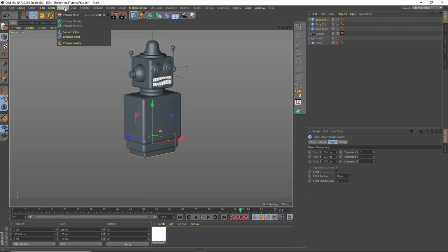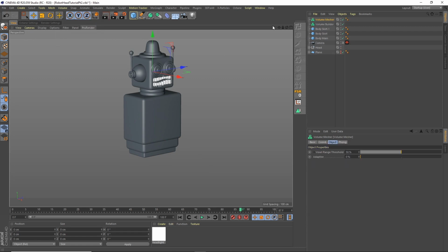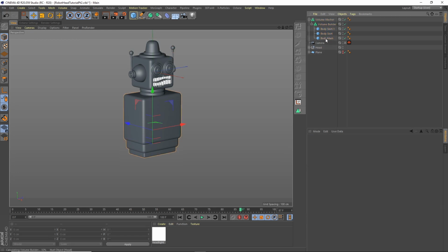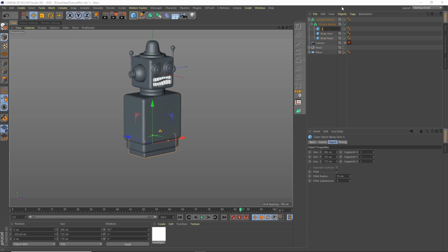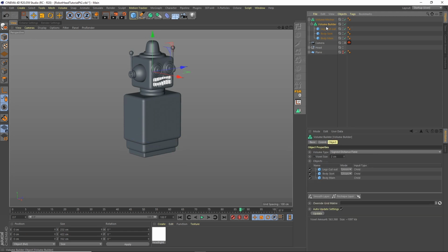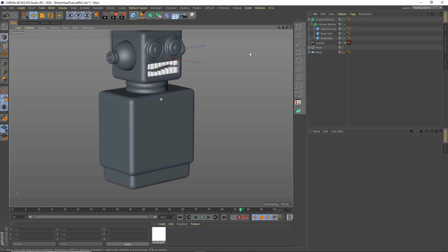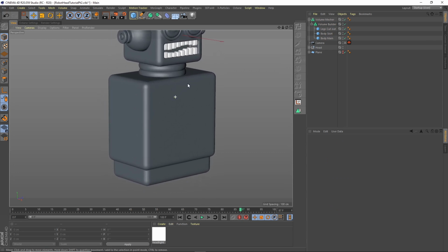Let's get a volume builder and measure. I'm going to set the builder to voxel size of 2, and let's put all of our items in, and then I'll do this legs cut out. So we want these two main items to be joined together, but the legs cut out, we want that to be subtraction. So let's add that as a subtraction. Okay, let's zoom in a little bit so we can see what's going on.